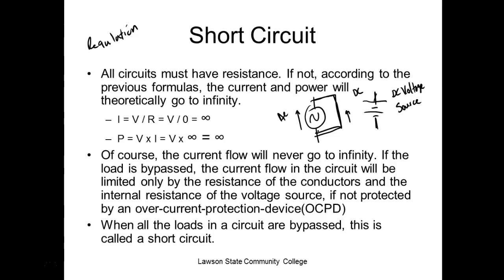Its resistance goes up. Your generator's trying to put out 14 volts. Now it can put out 3. This resistance goes up. Your regulator's saying, hey, I can put out a little more voltage. It'll go up. And the current's the same, right? You understand. And the wires get what? Hotter. So what's going to happen eventually? The wire's going to burn up, or your alternators.